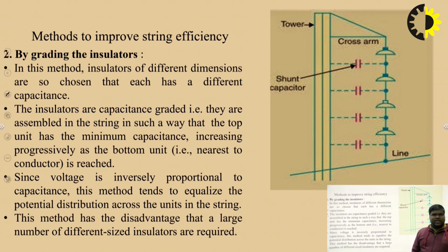So the other case, grading the insulators, is another technique. In this method, insulators of different dimensions are so chosen that each has a different capacitance.